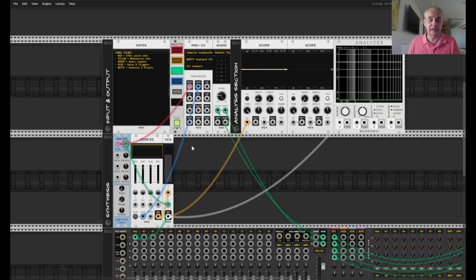In that situation you can have really strange alias behavior if you don't know exactly what you're doing, especially in the higher notes, where you think you are playing the chromatic scale, for instance, and then suddenly halfway down or halfway up the chromatic scale you hear the VCO making a jump downwards in frequency, because suddenly one of the harmonics aliases back to a much lower frequency, and that can sometimes be very audible and also very unwanted and unpleasant.